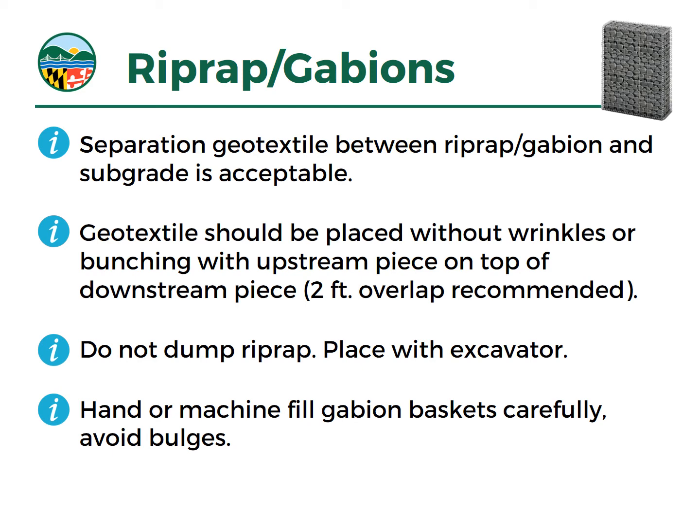Same with gabion baskets. Place the rock in them carefully. It can be machine placed. Hand placement is also good, but you don't want to have them bulged out or overstressed, because they won't function as well, and they could end up damaging the basket itself if you just dump things in there.